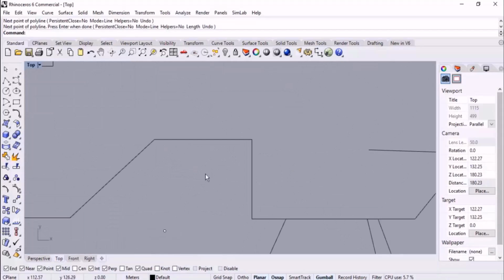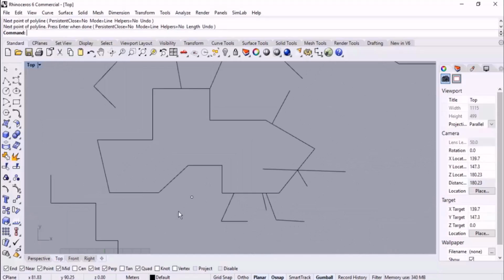But if you want one of these object snaps to be activated for a while, like midpoint, if I right click on mid, as you can see, it deactivates others but midpoint. Right now the only active object snap is midpoint. We can reset it to the default mode by a right click. This is very practical. I want to repeat it.